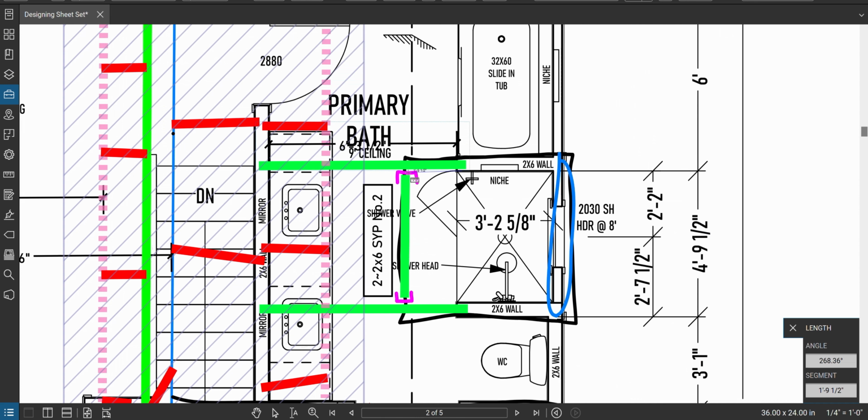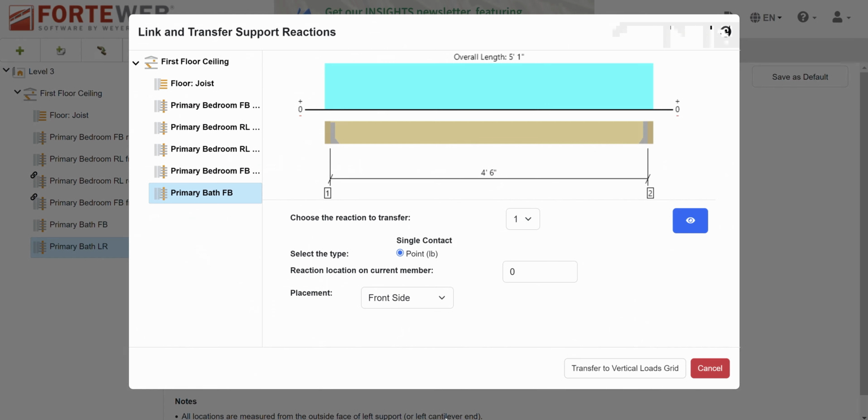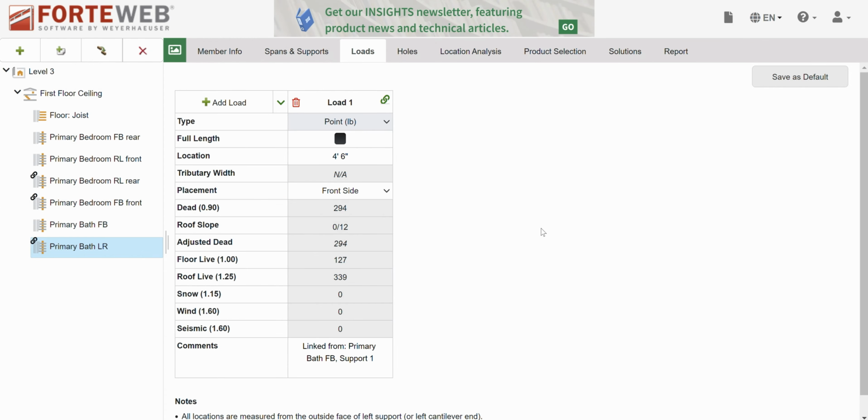From the right side in, well, sorry, it dimensions in from the left in the program, so left side in is about 4'7". If you're going to be conservative in this location, push the conservative towards the center of the beam. The load moving towards the center of the beam makes the situation worse. So if you're going to estimate towards the center, I'm going to say 4.5 feet. 4.5 feet on the front side is great.